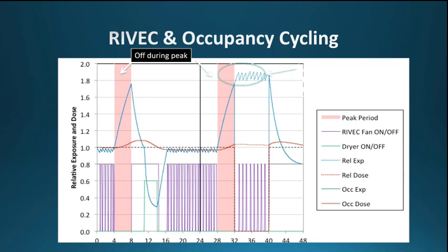In theory, one could extend that to a full year and still meet Standard 62, because it says the year average shall be less than 1. Instead, from a practical standpoint, a controller can't look back a year. We have it look back a day, and we allow some temporary excursions above 1 as long as the average gets below 1. And so that's the red line that you see.